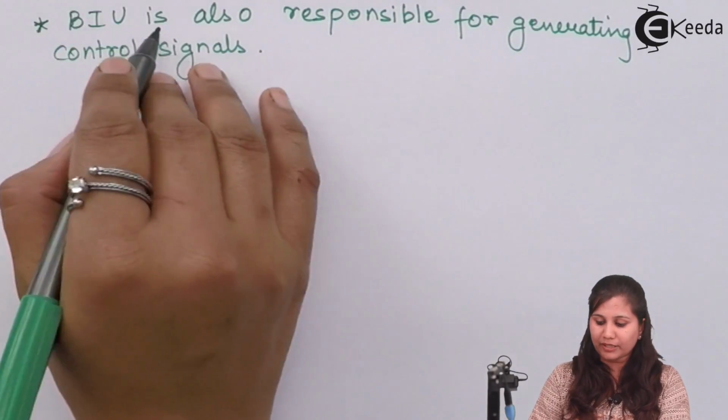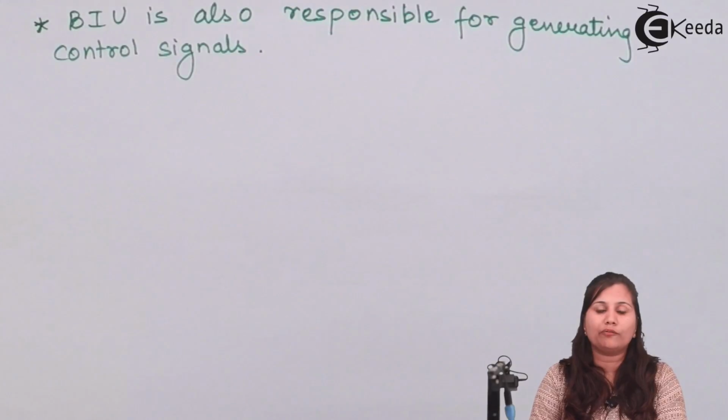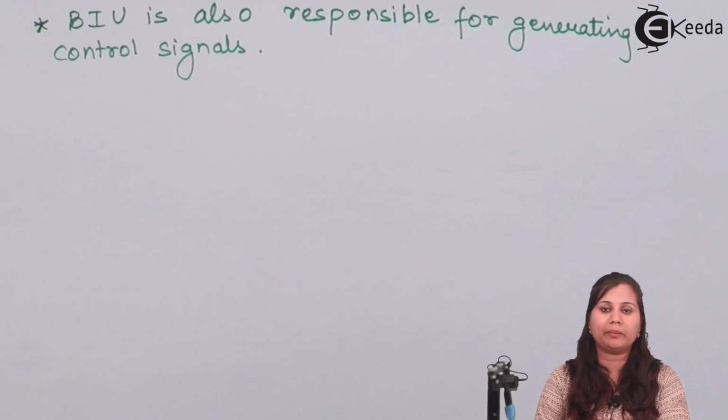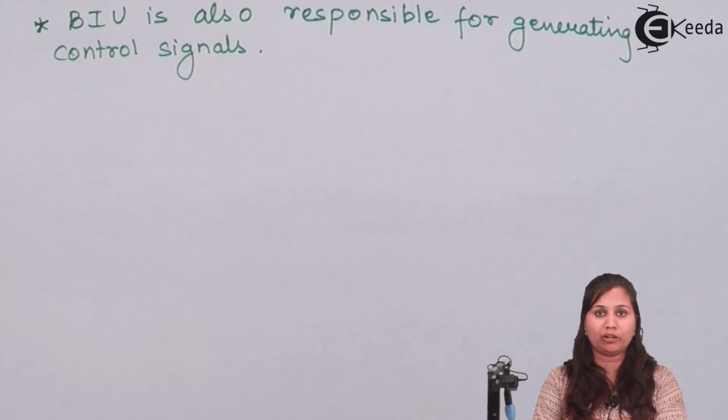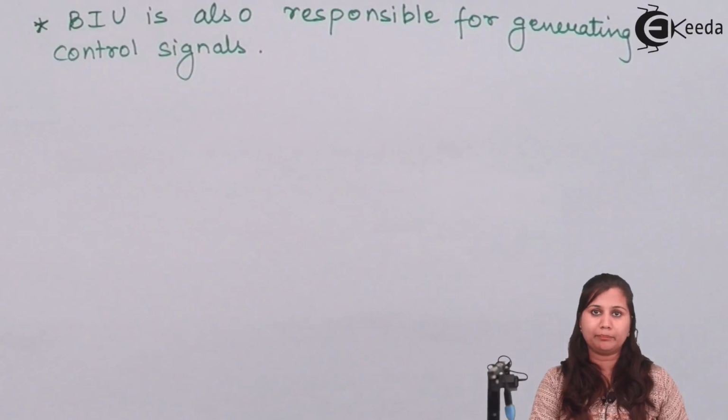So this bus interface unit is also responsible for generating the control signals for the memory and the input output operations, like memory read, memory write, input output read, and input output write. So those control signals are also generated by this BIU.